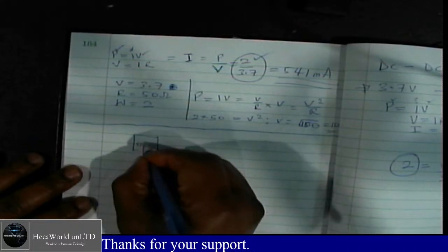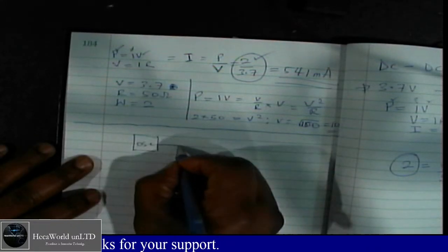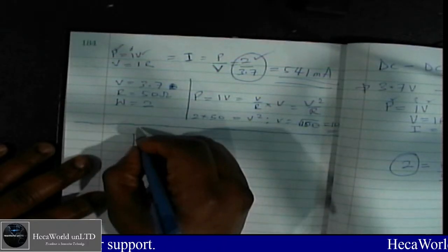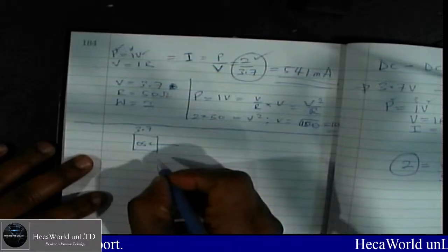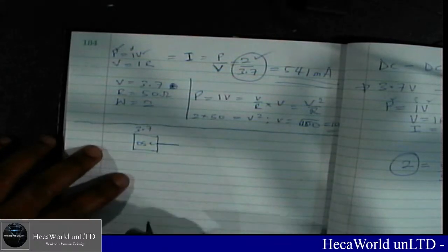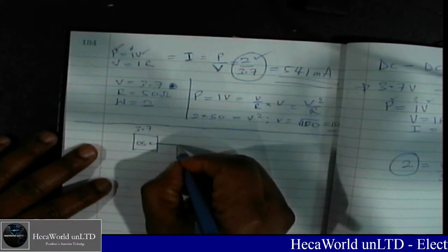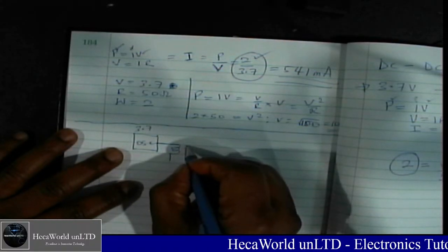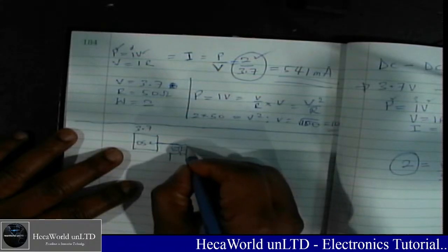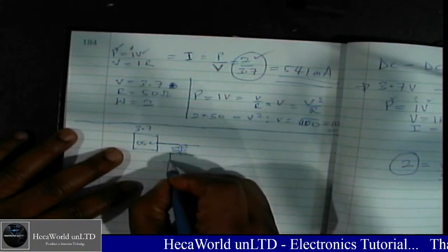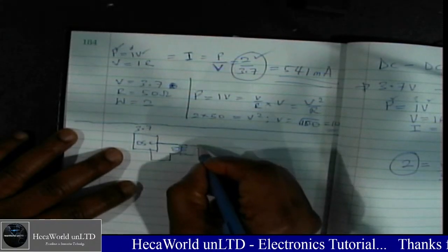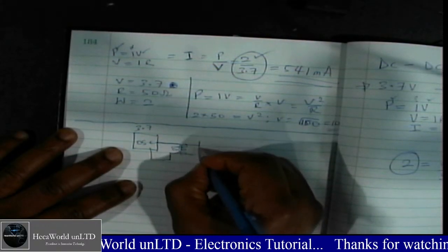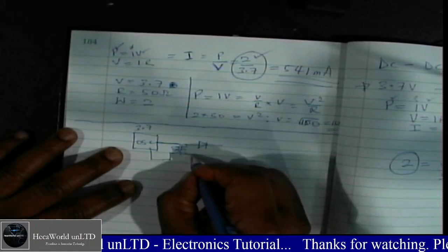I like block diagrams. I'll build an oscillator, power it with the power supply they gave me, 3.7 volts. So I'm going to build a 3.7 volts inverter. And then my oscillator will have a transformer, a step-up transformer. This step-up transformer will then go through a bridge rectifier or any form of rectifier. For simplicity, let's just do a simple rectifier.